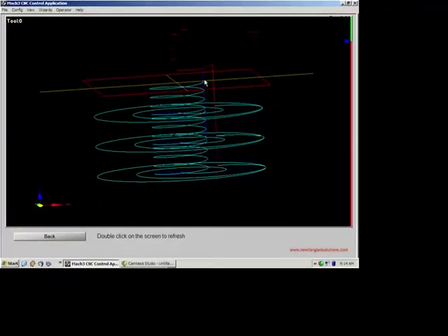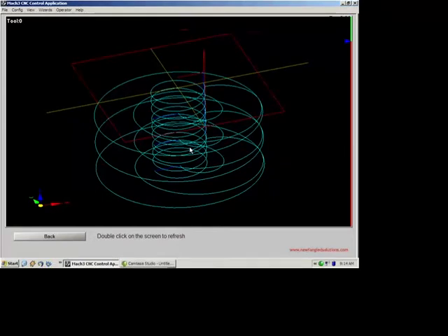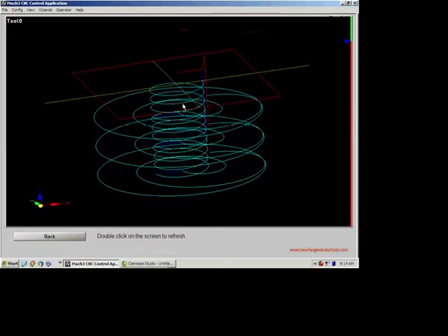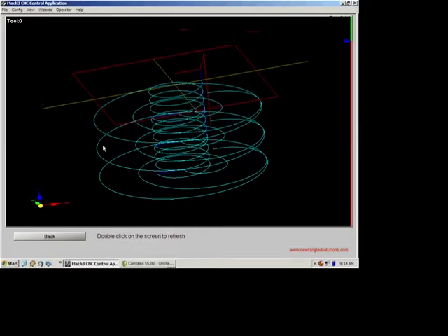So it comes down to the surface of the part and comes down in a 3-degree helix. This is actually helpful because you can bump your feed rate way up and actually cut in relatively quickly without ever getting burrs and stuff pulling up as much. This works particularly well in wood. You could take a fairly soft wood, and by helixing down into it, the wood won't stick to the tool as much. And in metal, you can actually cut a little bit faster going down.